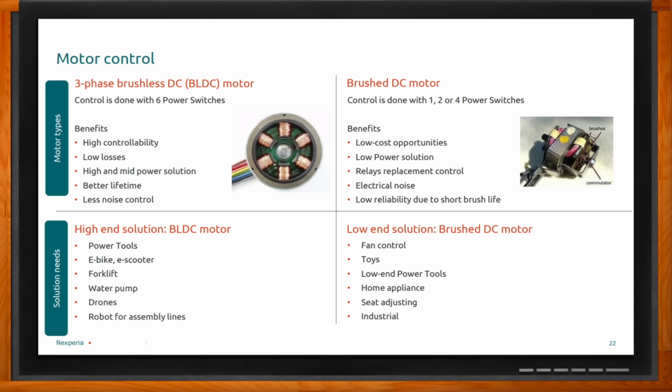And the BLDC motor, you can control that with pulse width modulation, and you can run that at much, much higher speeds instead of just running it at 50 hertz or 60 hertz. 60 or 50 revolutions per second versus, let's say, you can do 1,000 revolutions per second with the BLDC, or you can do more than that, 10,000 revolutions per second, or a lot faster than that, depending on the motor itself, the size and the controls. So for applications that require high speed and high torque, the BLDC motor is indispensable. And that has to work pretty much from a zero torque application, so zero load, to the maximum load.